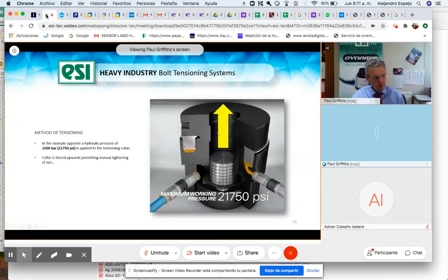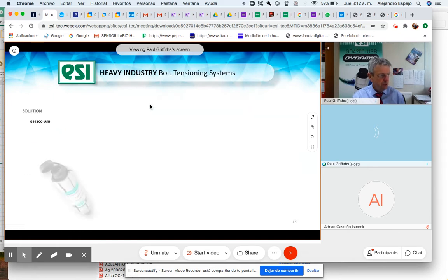Then we stretch the bolt upwards, so the nut then moves away from the surface, and simply turn it to this position and then release the pressure. So what you have is a tensioning of the bolt and the perfect tightening of the nut without any friction, and that guarantees that the two components, the two flanges, come together with even torque at the same time. Quite an interesting one, really.